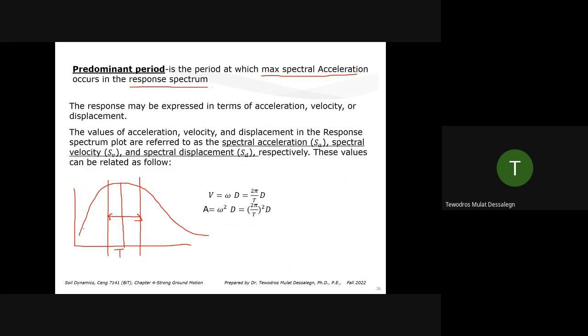It's not that smooth usually. You'll have it much sharper than my plot here. The peak value can be here. This is what we define as the predominant period. And you want to stay away from the peak value range. Or you want to design your structure somewhere here or somewhere here. And if you do it here, make sure you introduce some damping and you design it well, the reinforcement and everything. It's going to be costly, because you want to avoid cracks.